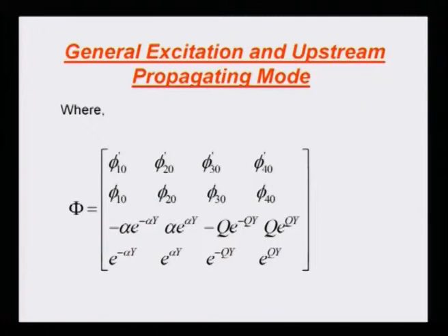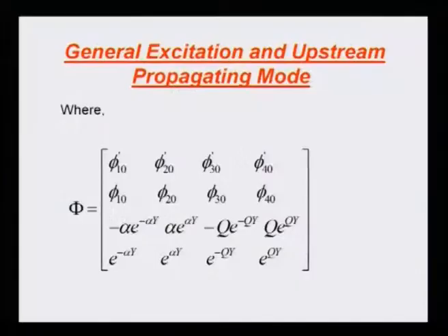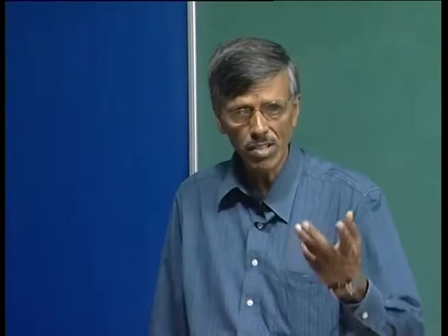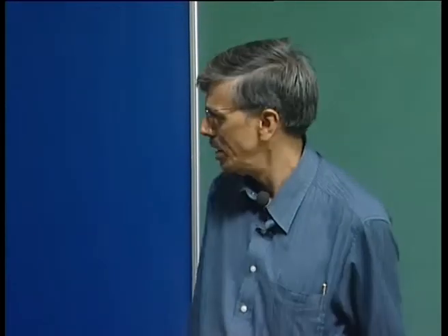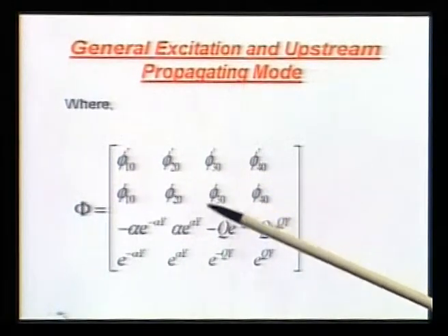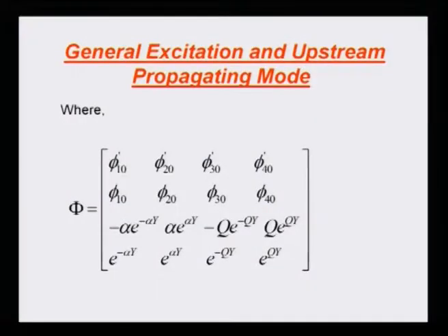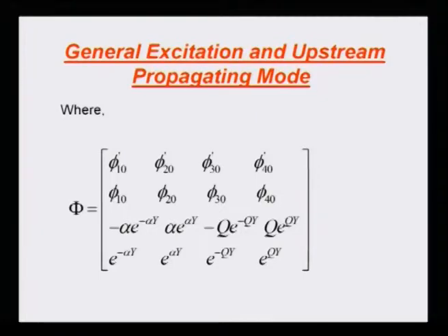Since we know the exact structure of the fundamental solution in the free stream, we could write down these last 2 rows very explicitly. However, inside the shear layer we have no direct way of finding them analytically. So, at the wall we do not know them, but we just know their functional form, in terms of the 4 components, and we left them as they are. Now, since this free stream excitation would be imposed at a very large y, we can see that some of the parts can go to 0.